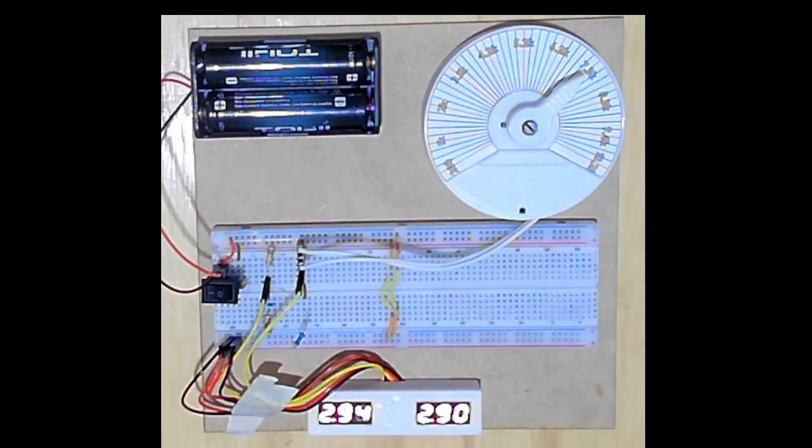So this one is close to 7.3 Ks. So that's maybe a 7.2K, 7.3K resistor, right? So with this little circuit, with the Wheatstone bridge, we are able to measure resistances and to obtain exact values of the resistances, right?